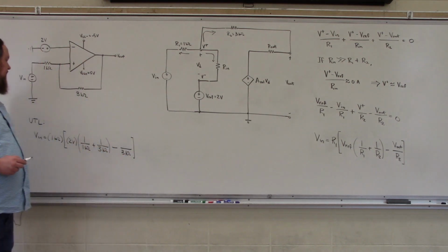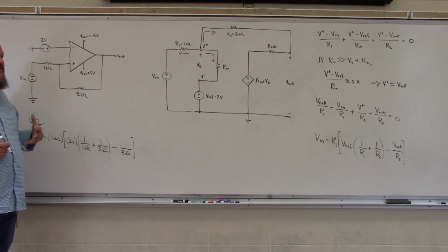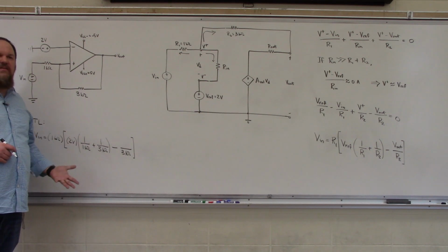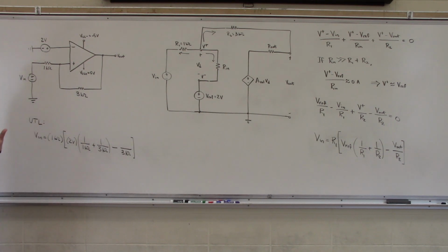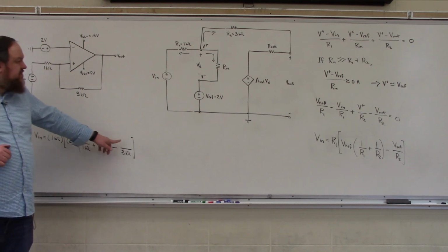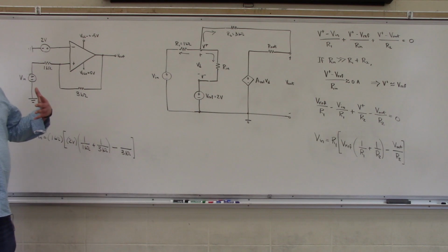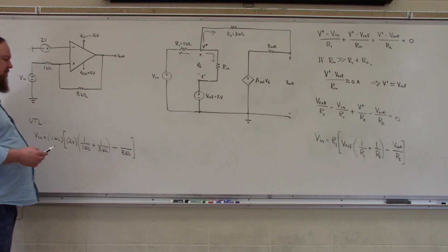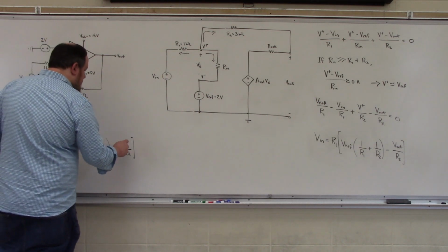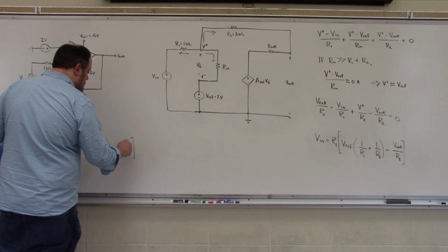The something that I have omitted here is the output voltage that we need to be using. This is where a lot of students struggle, okay? So since we are trying to determine the upper trigger limit, or the voltage that causes our output voltage to swing high, then the output voltage that we put here must be when it's at its low value, VCC minus, or in this case, negative 5 volts.